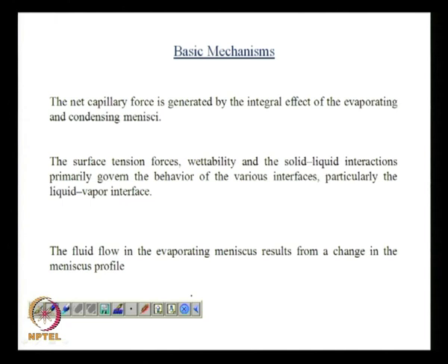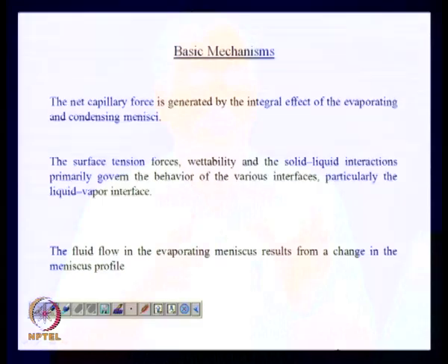And when we talk about a liquid film which is becoming thinner and thinner as we progress towards the hot spot, then additional forces will come into play. For example, when we think about a meniscus, at the macro meniscus where it is thick, the effect of intermolecular forces will never come into play, but the moment the meniscus starts to become thin, additional forces such as long range van der Waals forces will become increasingly important.